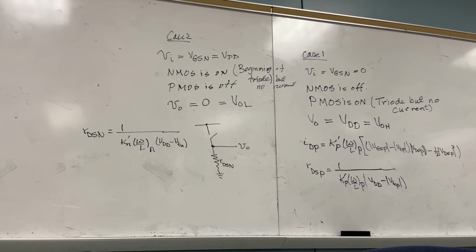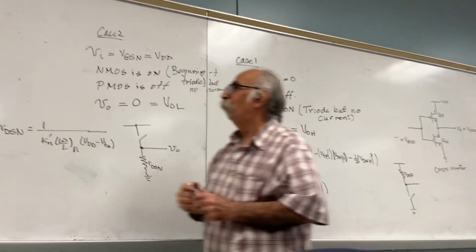Static power means what? Remember, when you are dealing with digital logic, you have how many states? You have 0, you have 1, and you do have the dynamic, when the logic is switching from 0 to 1. We are talking about the static right now. How much is the average static power dissipation? 0. Why? No current. This one here is 0.